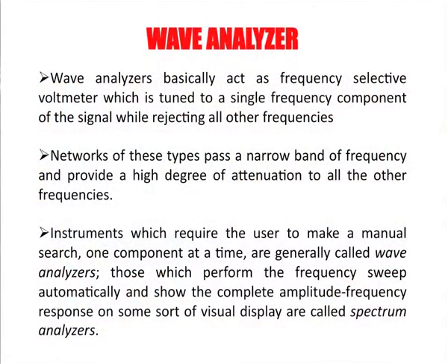There are some waveform analyzers which automatically sweep the signal and show the complete amplitude frequency response variation. Frequency response means here we are talking of the variation of the amplitude with the different frequency components. They are displayed on the display screens, and such types of automatic wave analyzers having visual displays are called the spectrum analyzers.